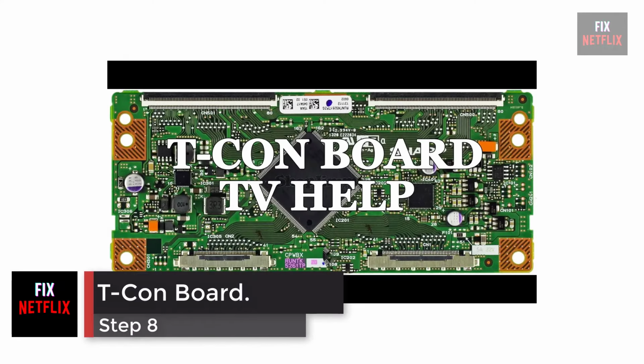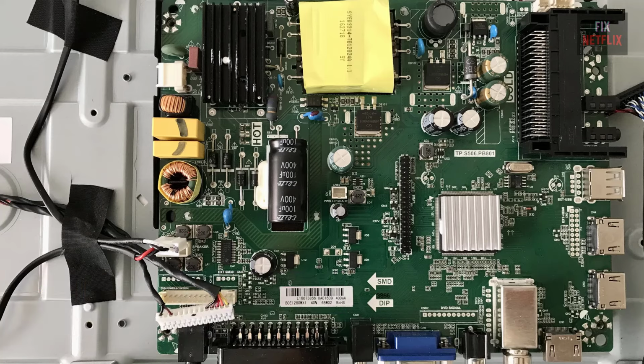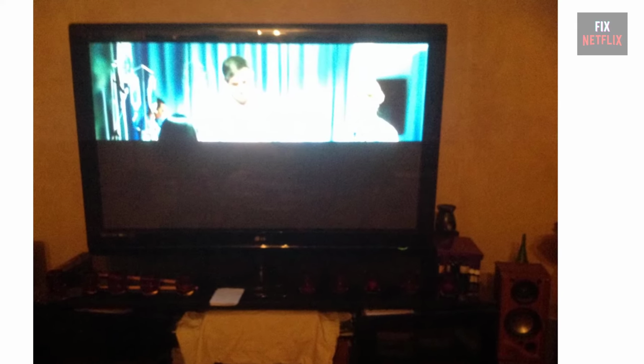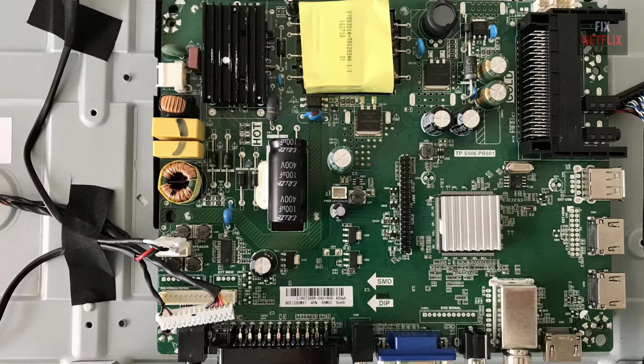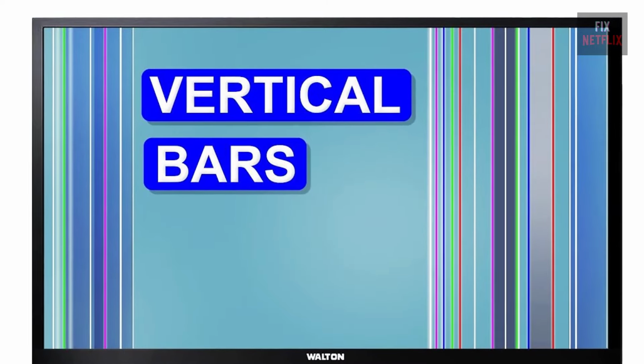Step 8. TCON board. This check for the TCON board also touches on the condition of the main board. Note that problems that show up on half of the screen, like bars or such, point to a failed main board, as the TCON board errors show up on the whole screen. As an example, if an error like bars on the screen is on the whole screen, it is likely the TCON board.